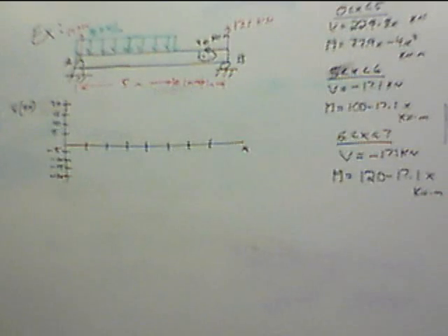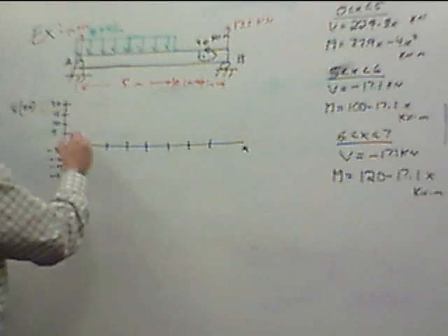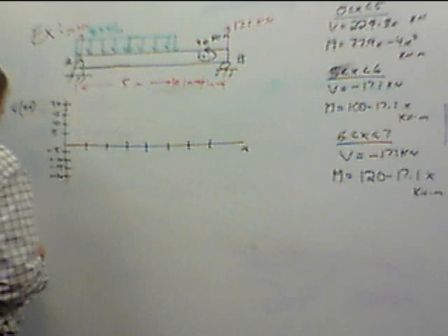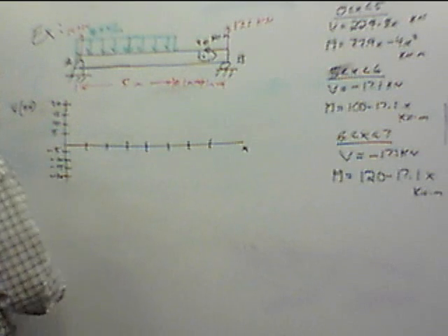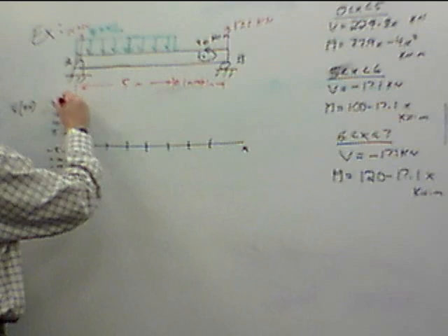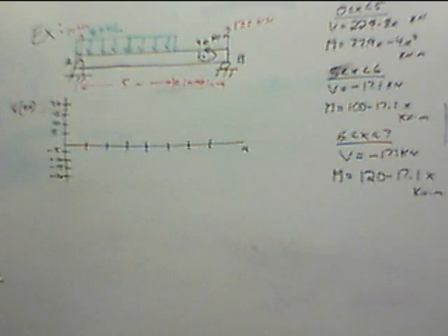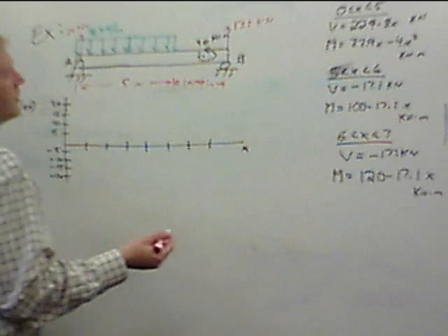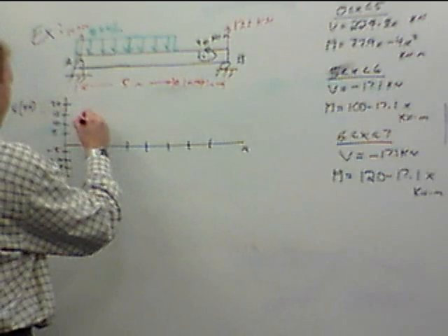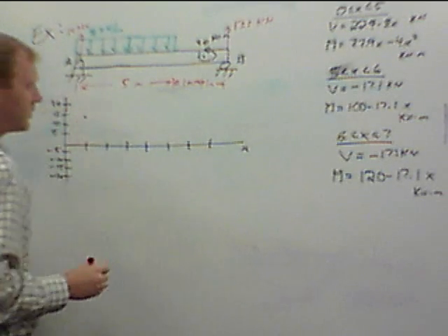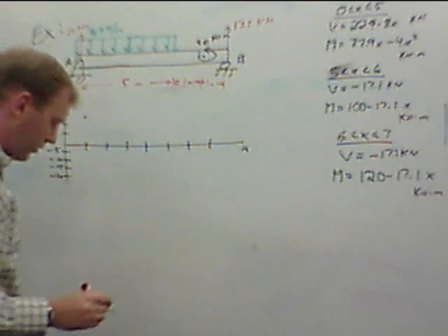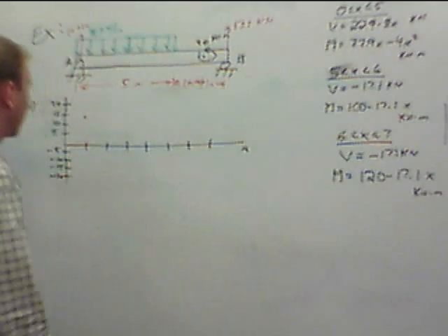All right, so starting at 22.9 at 0, I'll do this in a different color. 22.9 will give me a value here. And then the shear is just going to decrease linearly by 8. So 22.9 minus 8 is going to be 14.9 at 1. Down 8 more, oops, is going to be 6.9.